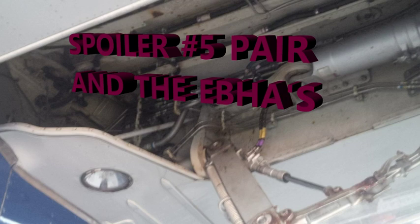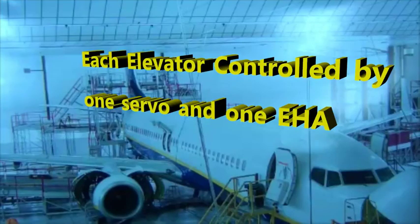And then we've got the computers that are in charge of moving certain control surfaces. So for example, and I'm going to go over some of this so that you, again, don't have to memorize obviously all of this stuff, but your elevator control, you have one of each. So you have one conventional servo control, and then you have one electro-hydrostatic actuator that's in damping mode.